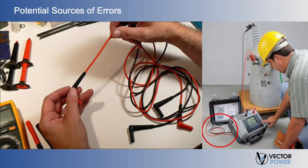Now let's talk about potential sources of errors obtained in our measurements. Beware of low-quality leads whose voltage rating is less than the test voltage that's being employed. It is extremely important that the only leakage currents during a measurement are those developed by the insulation under test. If the leads produce leakage, you may measure lead insulation resistance rather than the item under test.